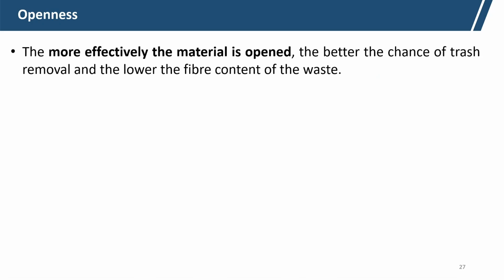Now, the openness is calculated by the openness tester. The more effectively the material is opened, the better is the chance of fiber cleaning. As I have already mentioned, new surface will come. If I see this lump of fiber, trash particles are there. Now, we are trying to open the same fiber, mass m milligram.